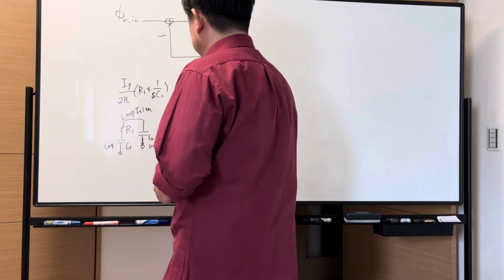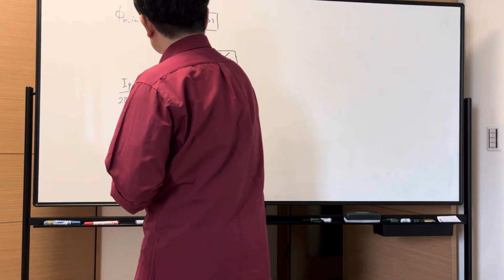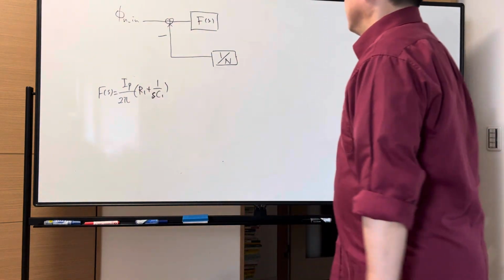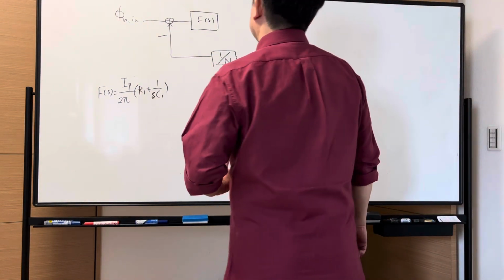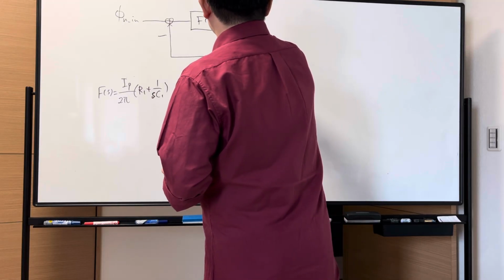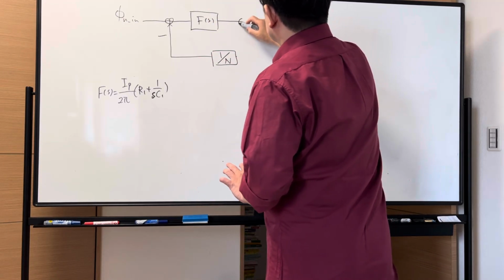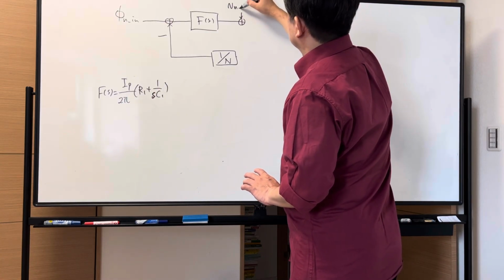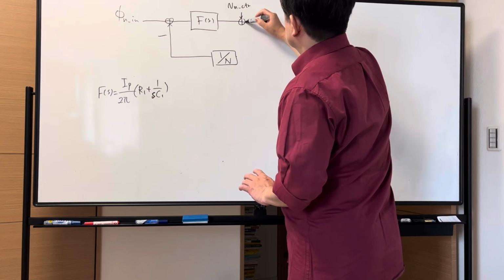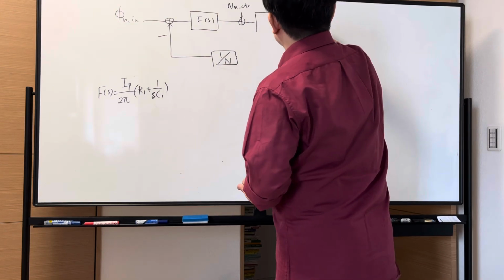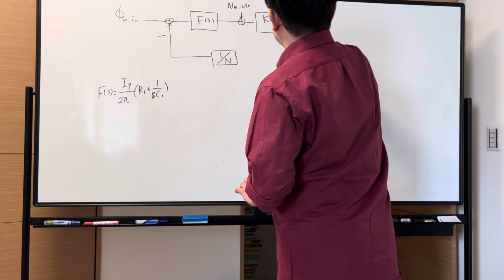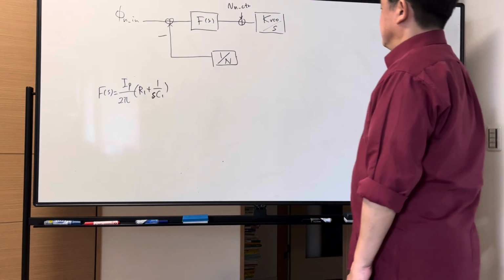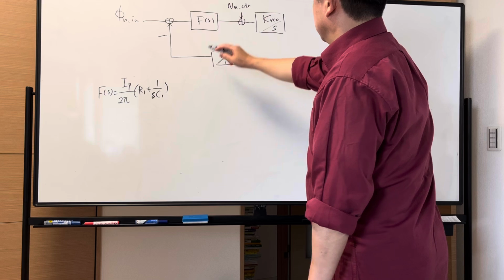And then this F sub F of s is described like this, for nominal cases. From here we have noise or a control signal, followed by the VCO, which has a transfer function of K VCO gain divided by S. Each is an integrator. This is also an integrator like this one.